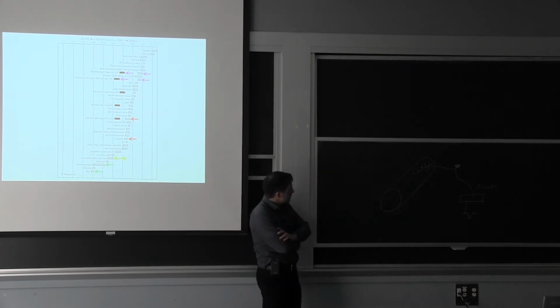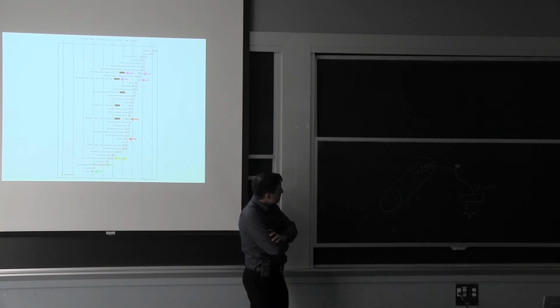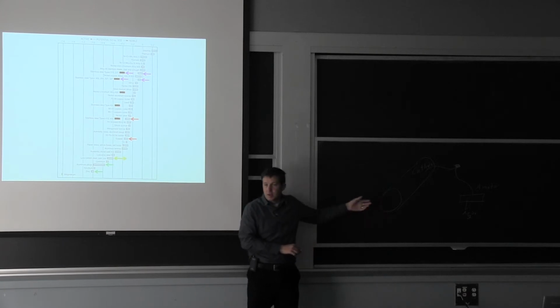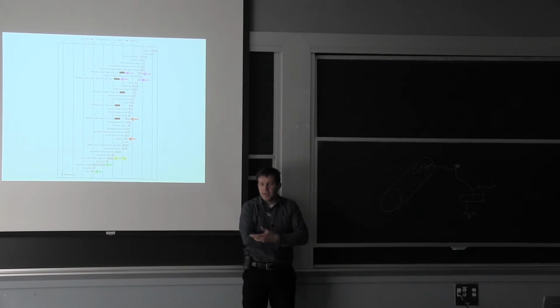There's something that's missing with this. First of all, if you ground it and you're effective in grounding it, it's hard to get that high potential because you need a couple volts at that point. If all you're going to do is really passivate it, and at a couple volts into the ground, you're going to have to supply a lot of current too. So you're talking about polarizing the system essentially, and I've not seen it done. And there may be other, more fundamental reasons in terms of even creating that condition.